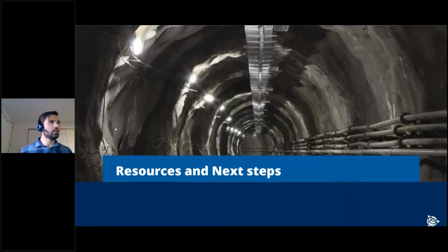Cool. And then another one came. Go ahead, Jeff. This is impressive. Can I use the point cloud of other scanners to achieve it, like the X7? Yes. So you can use any survey data. So if it comes from a total station or a CSV, and you can use any scanning data that can be imported into TBC. So X7, TX8, or even if it's coming from an LAS or an E57 file.